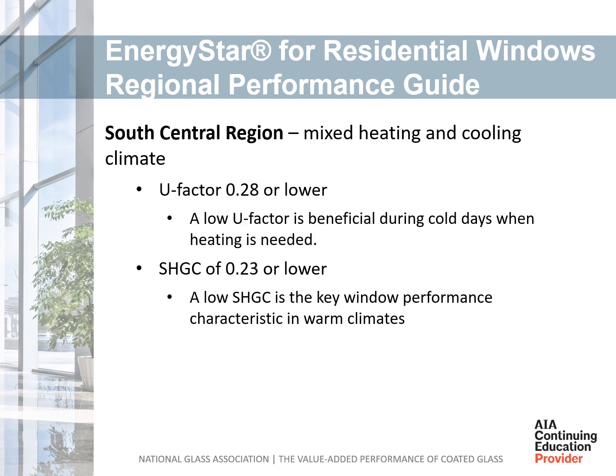The south-central region includes heating, but consists mostly of cooling loads, so is neither dominated by U-factor or solar heat gain requirements. In general, a U-factor of 0.28 or less with solar heat gain coefficient value of 0.23 or less is required.